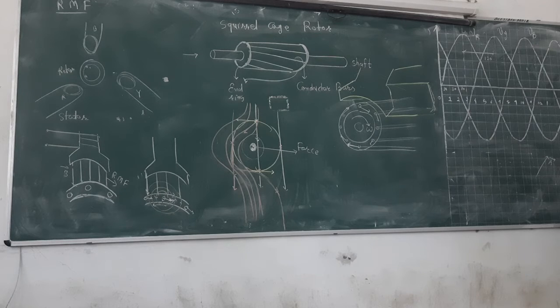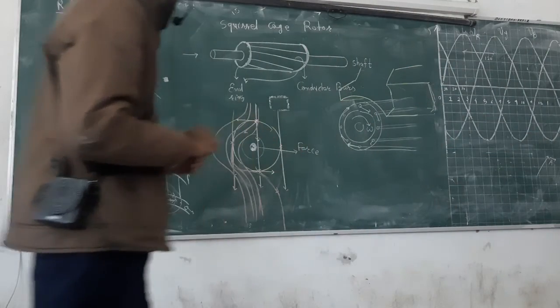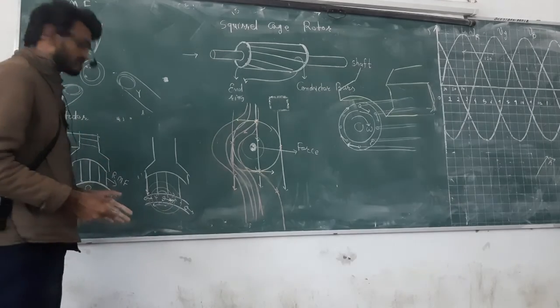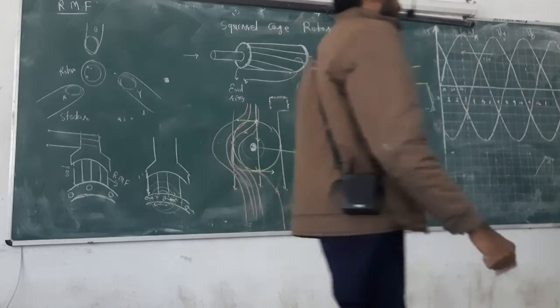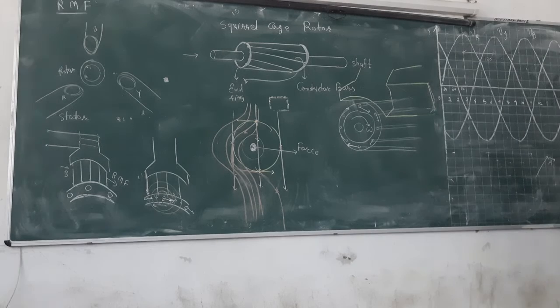It may be achieved, let's say, but some important phenomenon happens. Think about it. The hint is, let's assume that the rotor achieved 3000 RPM. Then what will happen to Faraday's law? How does the rotor induce current? Magnetic field lines must cut the conductor. The rotating magnetic field does not cut the conductor.